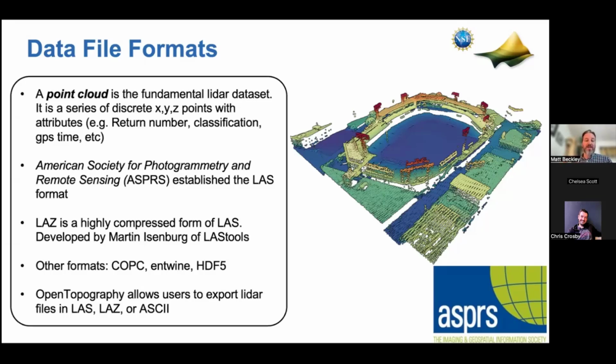the data comes into us, we allow users to export in three formats: LAS, LAZ, or ASCII. We sort of discourage ASCII because of the size of some of these data sets. Those file sizes get quite large and you'd be limited in terms of your job size. But it is a useful tool for education and things. So we've kept it around as a potential output format.